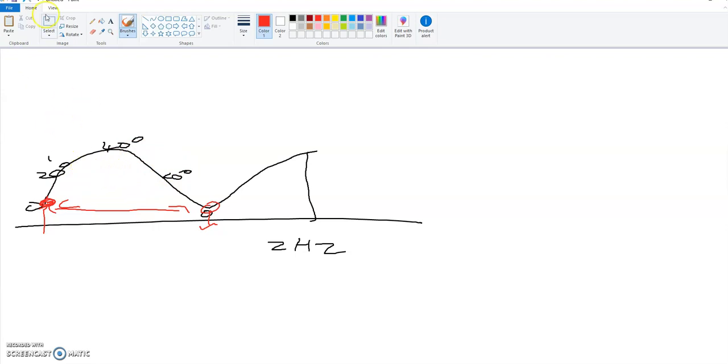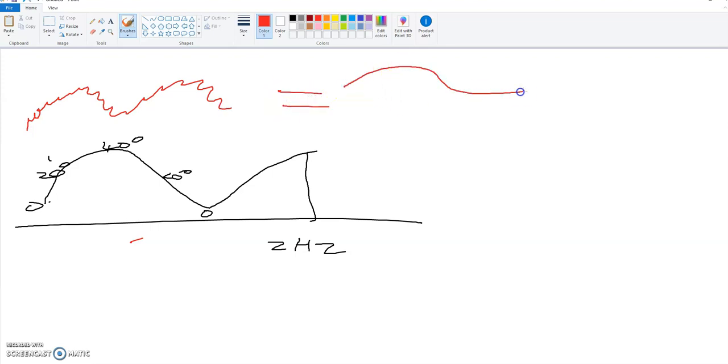This is now kind of called the Nyquist rate. You can Google this as well, Nyquist rate, Nyquist frequency. What the Nyquist frequency says is you have to look at your highest frequency and you have to sample at least double that, double the speed of your highest frequency. Now the thing is here, this is not our highest frequency. If we look at our noisy signal, remember the noisy signal looks something like this, which was a combination of a high frequency and a low frequency.